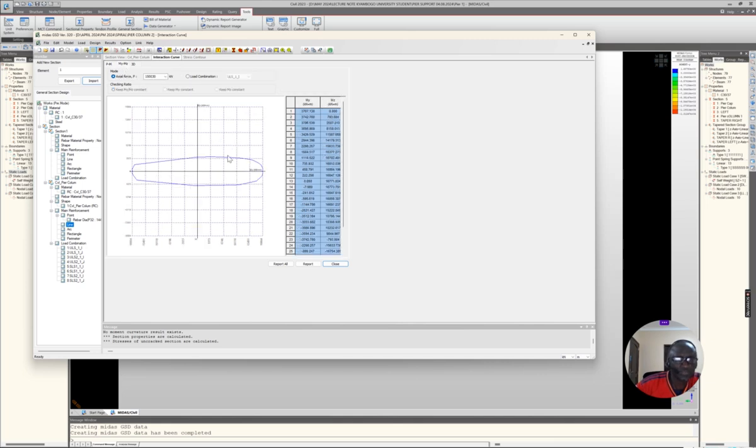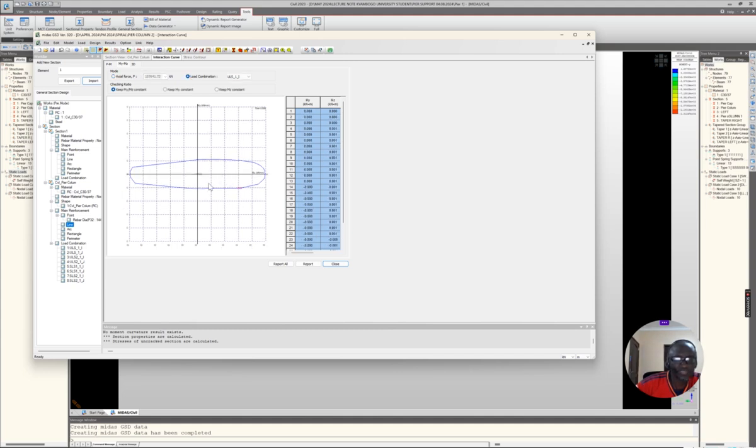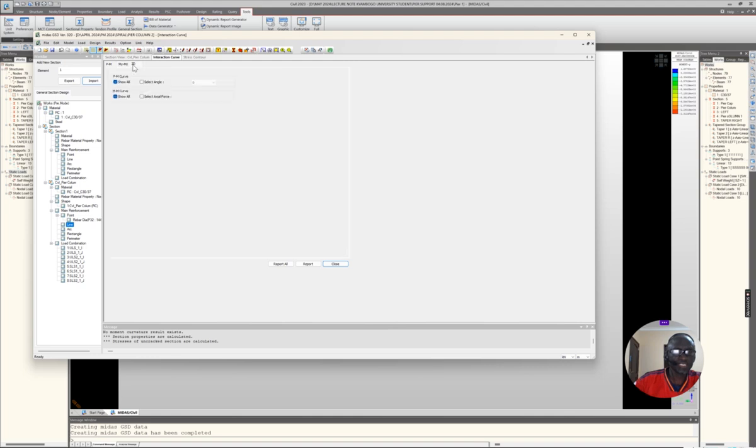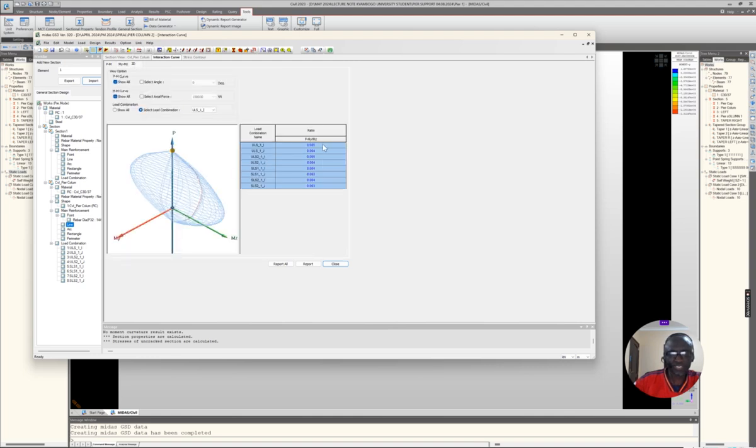Now if you come to these and then you also view, this is the My Mz, you see the moment is more or less 0, the reinforcement more or less 0 in here. So we have over design of that. Though don't worry about this, because this was an arbitrary value. All these load combinations, they're all here. Then the 3D curve, you can see the ratio of P, My or Mz is negligible. So that is where the engineer goes back and begins to review his section.